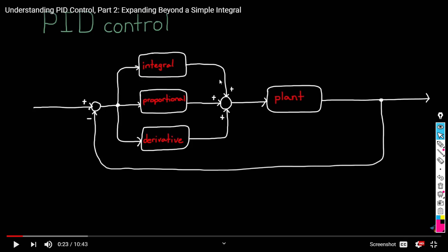Also for the integral term, you don't consider saturation of the actuator in simulation, but actually you can simulate the saturation. We learned how to simulate the saturation last time, so we can simulate it. We can add noise; we already added noise before. So now we will learn about the effect in practice of saturating the actuator when I have an integral term.